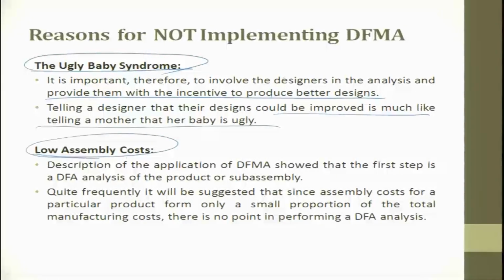Then low assembly cost. The description of the application of DFM shows that the first step is a DFA analysis of the product or the disassembly. Quite frequently it is suggested that since assembly cost for a particular product forms only a small proportion of the total manufacturing cost, there is no point in following DFA. So, that is what they say. They say that assembly cost is too low, so why do you follow DFM?